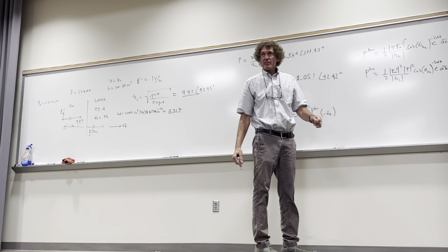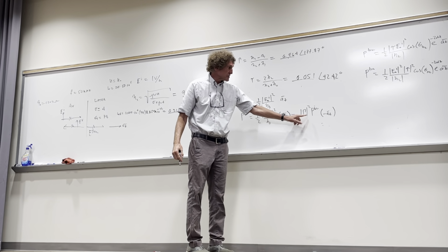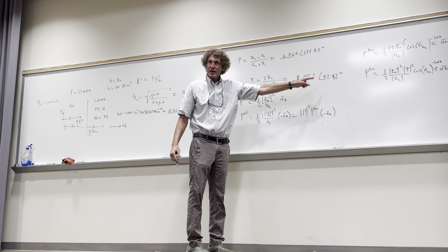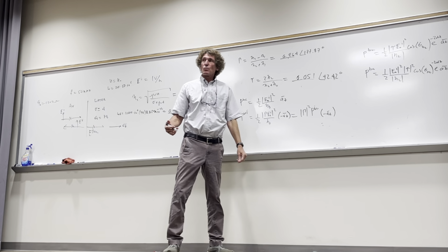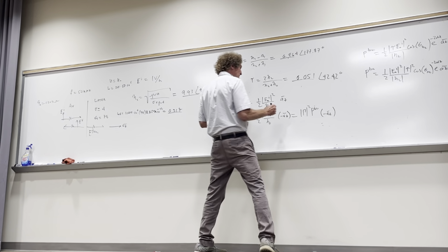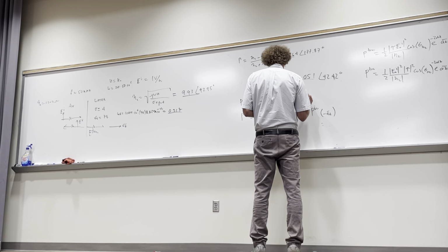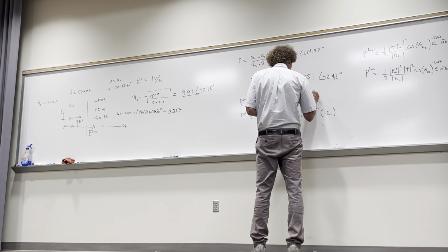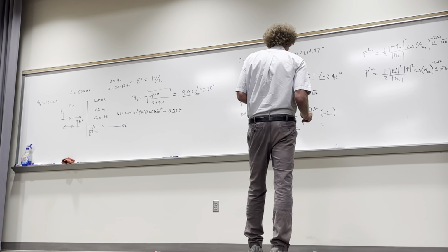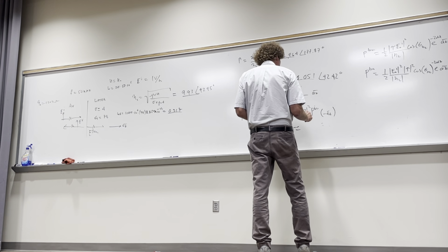Now one thing you've got to be careful with, remember here, we could get away with saying it's just reflection coefficient squared times power density. Now you can't do that over there. Y'all follow me? Can't do that. So I assumed 1 volt per meter, because it's all ratios anyway. If we do 1 volt per meter, then over here, this one comes out to a power density of just 1 over eta naught, and this would be just 1 squared, and it would be a_z. This one is going to be the reflection coefficient right there, squared, whatever that is, times the incident power density.